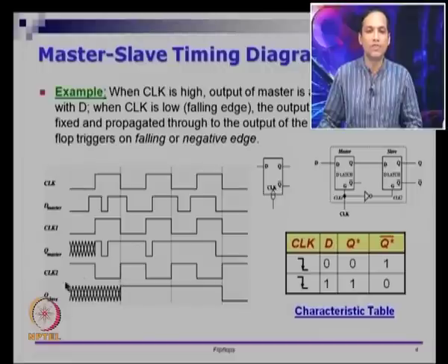So we don't worry about what is happening here for now, because this is the first time when CLK2 is on, right. So we know all the data input as well as, so here the data is not known, clock 1 came on, so we do not care about this, and CLK2 is off, so we do not care about Q of the slave here.